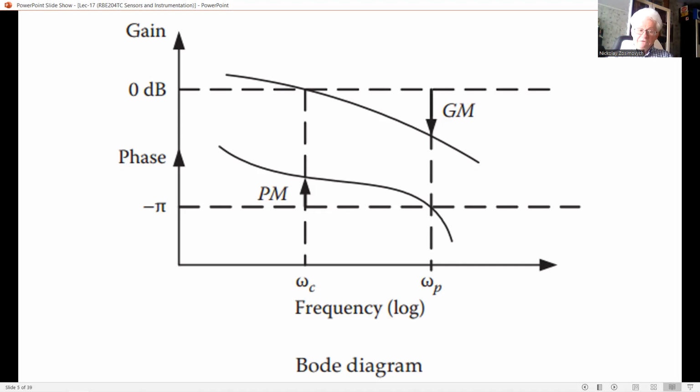Additionally, if at this particular frequency the loop gain G times H is unity, a sinusoidal signal with this frequency will be able to repeatedly travel through the loop without ever changing its phase or altering its magnitude, even in the absence of any external excitation. This corresponds to a condition of marginal stability.